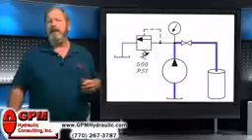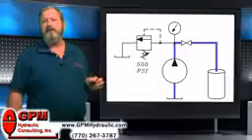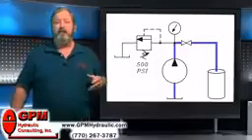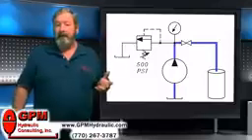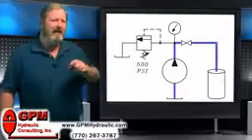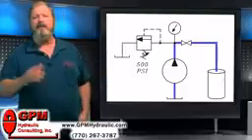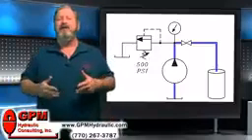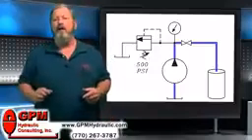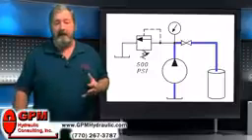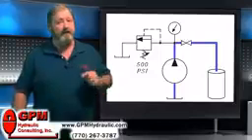So does that mean that I need to change my pump? Well, of course not. A brand new pump would perform exactly the same way, would it not? But let me ask you a question. How many times have you seen a pump changed for no other reason than because the gauge read 0 or lower than someone thought it should be? Personally, I've seen it hundreds of times, and it's typically a mistake.